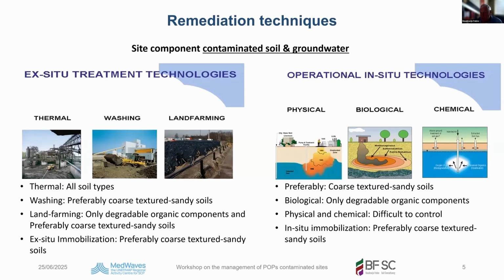And in some cases, some additives are being introduced, but then we come to the chemical part. But soil washing is preferable, and for soil washing, as I said, you use a hydrocyclone, so you separate the contaminant part and the non-contaminant part. But to use soil washing demands that your soil fraction where the contaminant is... you have to pilot it always. So you cannot just do it, you have to pilot. But I will come to that later.